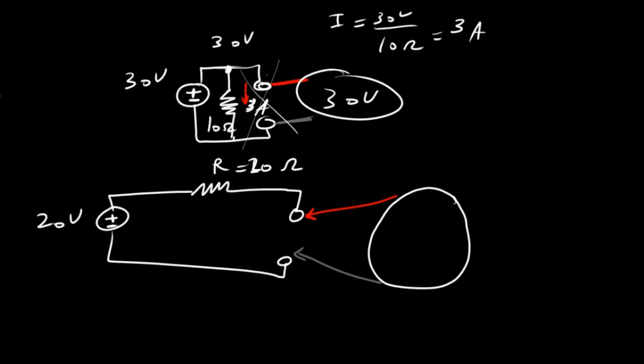Okay, I'm assuming you've tried to answer this. Applying Ohm's law, V is equal to IR, to determine the current flowing here, I is equal to V over R. And you have to remember, resistors in series add. We know that the air gap has a resistance of almost infinity, or approaching that.